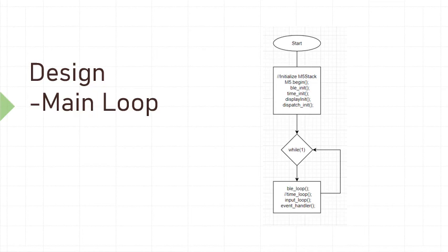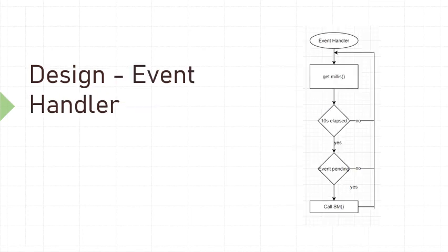This is the main loop that runs continuously, where it initializes all the peripherals in the hardware, and then goes about continuously updating the time, getting the temperature and humidity from the BLE sensors, and dispatching it to the display system. So there is actually a state machine that gets called every time there is an event. Here you can see that one event is the 10 seconds elapsed event, which will force the state machine to update certain variables.